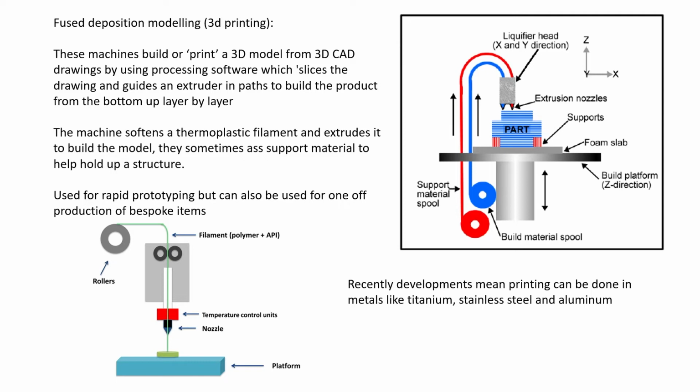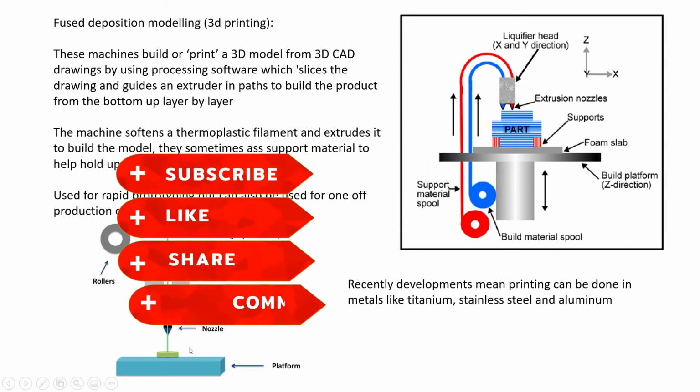If you've never seen a 3D printer work, say you've got the bed down at the bottom. I want to print on here. You have your filament, your roll of filament. We typically use PLA. It'll be fed in there, it will heat up, be fed through the nozzle, and it will stick to the bed. And layer by layer, it will slowly build up.